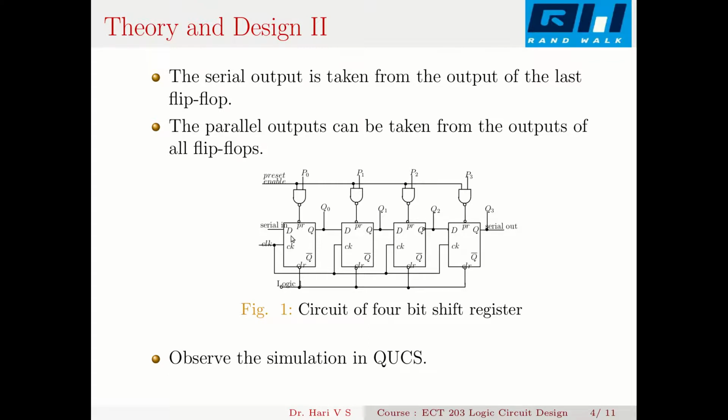Now this is your serial input. Here you can see that all the 4 flip-flops are clocked in parallel with a common clock. This is a synchronous circuit, and there is a common clear signal. This is for clearing all flip-flops.